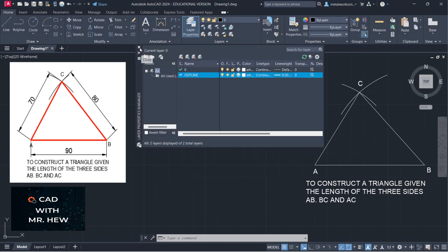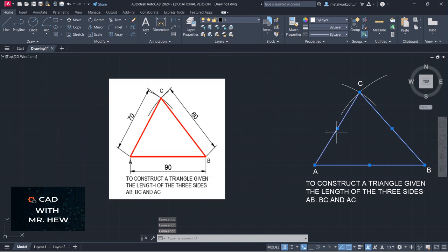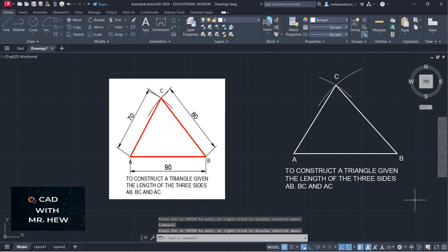So if you're using the traditional instruments such as the T-square, set-square, and compass, what you would do, you would use a 3H or 2H pencil to darken these 3 lines, right? If you don't have the 2H or 3H, you could use the H, but it's really the 3H I would recommend, okay? All right, so there it is, and we are finished, so we're good to go. To complete the drawing, what I need to do, I need to put the dimensions on the 3 sides, all right? So I'm going to move this label down.